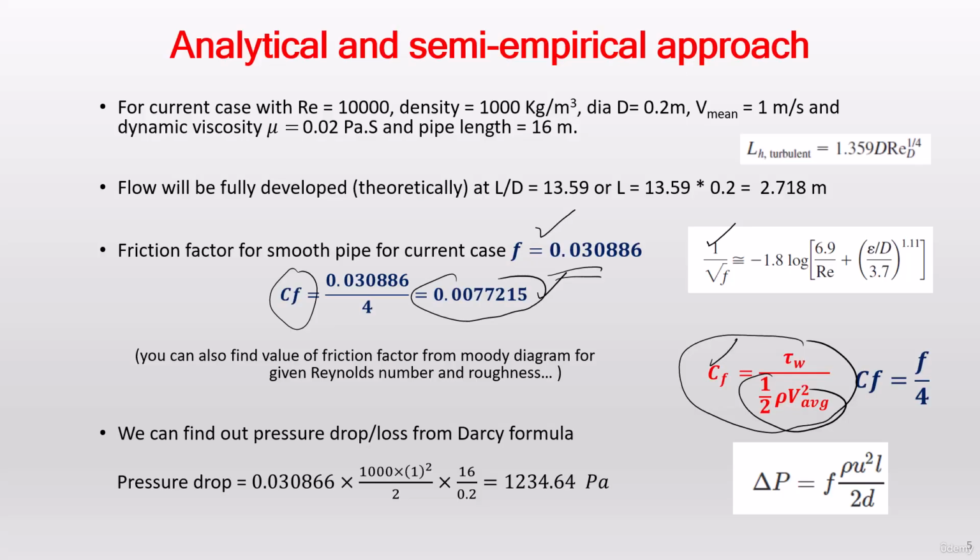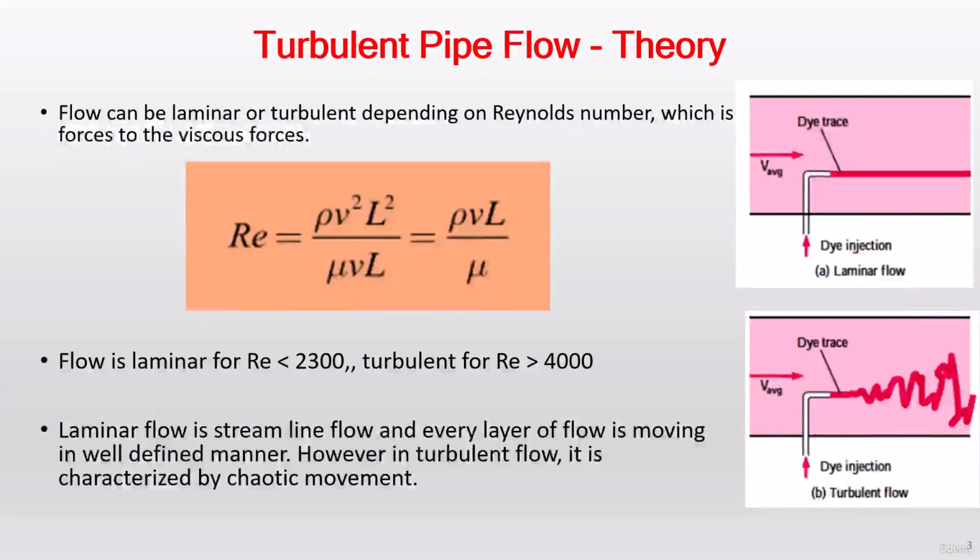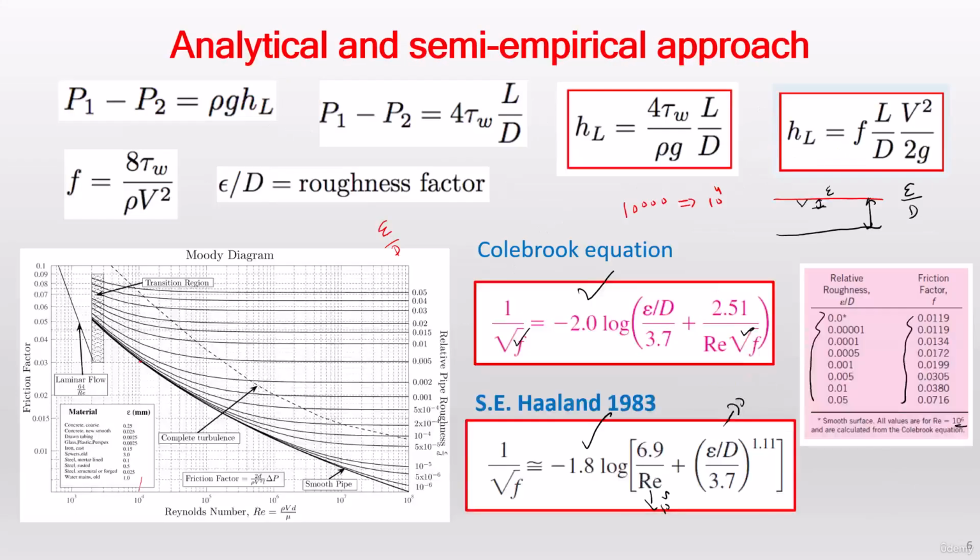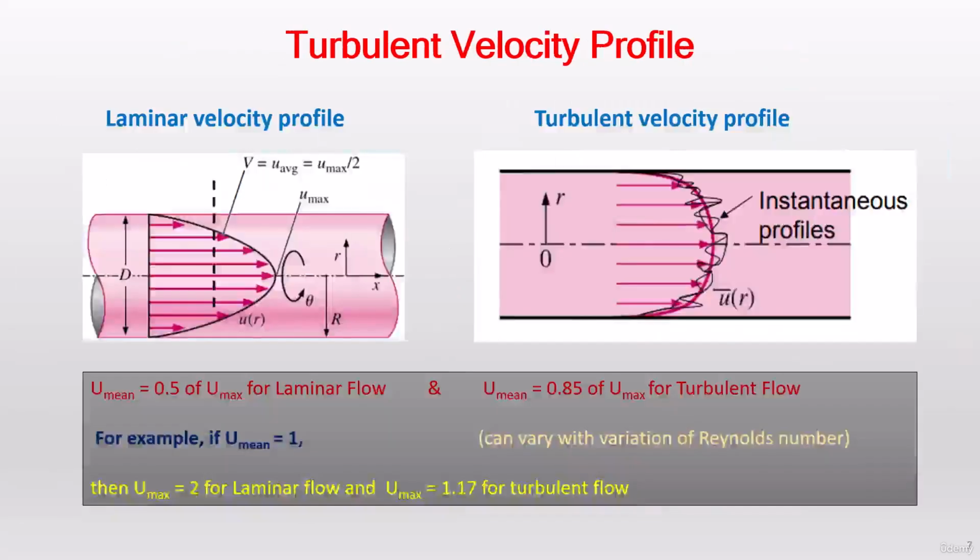This empirical correlation uses the external data, but definitely this is the best fit curve on that data from the experiments. Now I'm using the pressure drop from Darcy's formula with the Darcy friction factor, and the formula is still the same. The formula is delta P, this is delta P actually, equal to the friction factor times L by D times V square upon 2G.